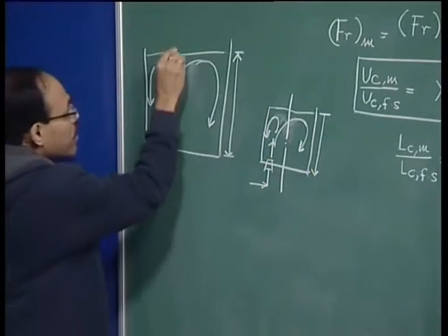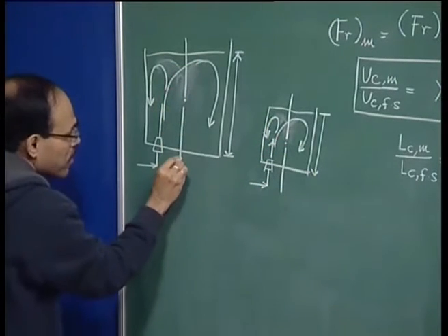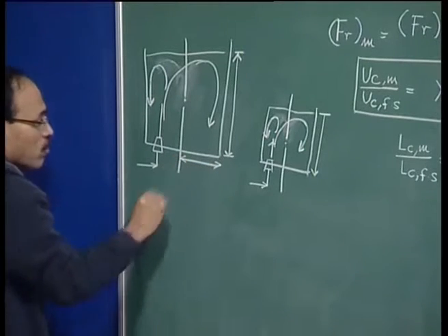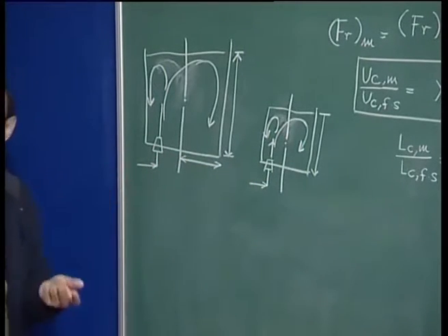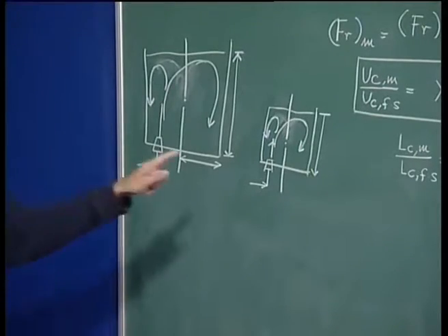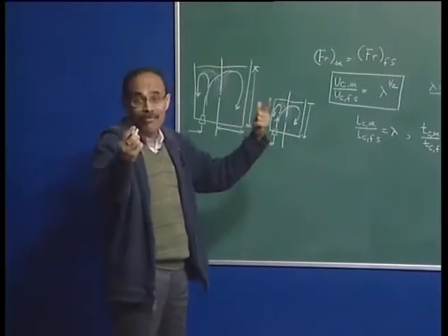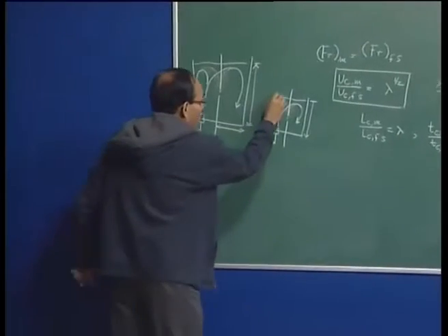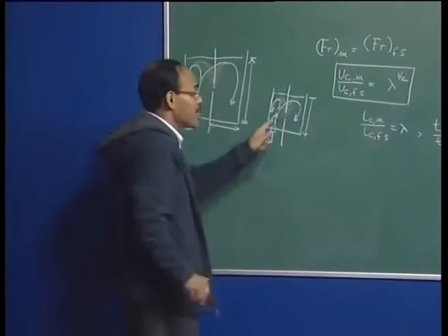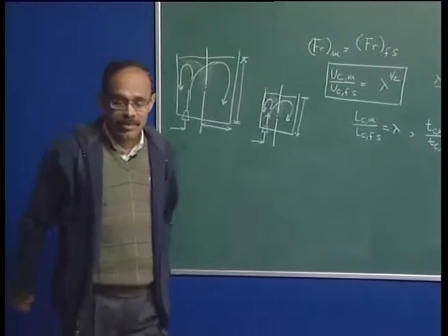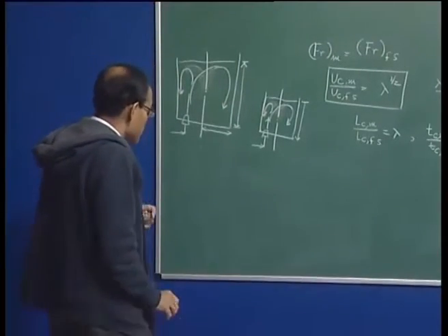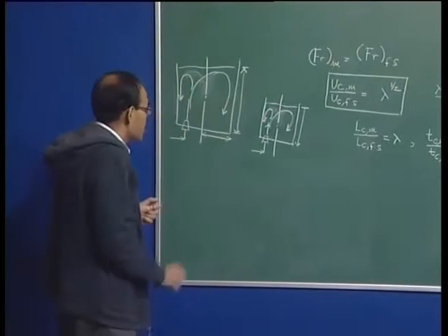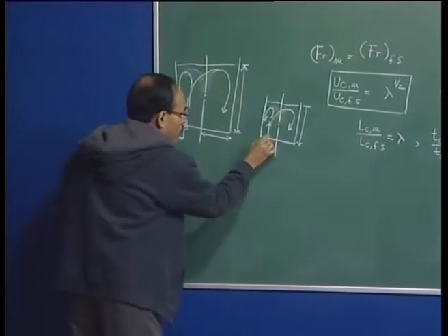This is the central line, and note that I am always drawing the porous plug displaced from the central line, because you remember that I said that this is to be converted later on to a ladle furnace, and in a ladle furnace we do not want the porous plug to be located immediately below the electrodes, because it is going to otherwise lead to electrode hunting or electrode consumption. That is why this porous plug is always displaced towards the wall.